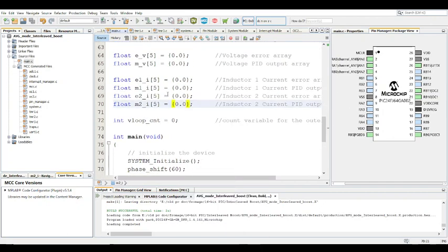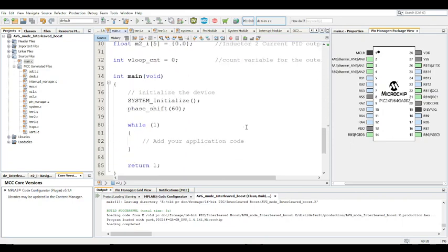And well, you might want to consider using, like I said before, dsPIC or STM32 or Texas Instruments or Renesas or any other microcontroller architecture that's optimized for this purpose, because Microchip is more like a multi-purpose sort of thing, and it's more robust in that sense, whilst those other ones that I mentioned are much more focused on digital power control. So they're optimized for those things.